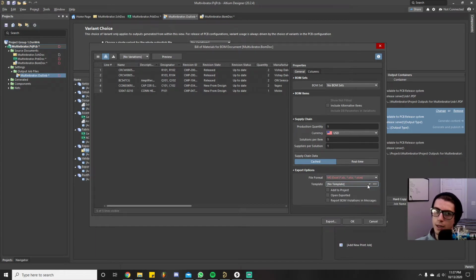This is super important. I can tell you from experience, it's really important to get your BOM templates formatted correctly, because you can make some major mistakes if wires get crossed between you and the manufacturing team. And these guys are usually third party, so that's how wires get crossed easily. Make sure you format your BOM correctly. So that's super, super important.